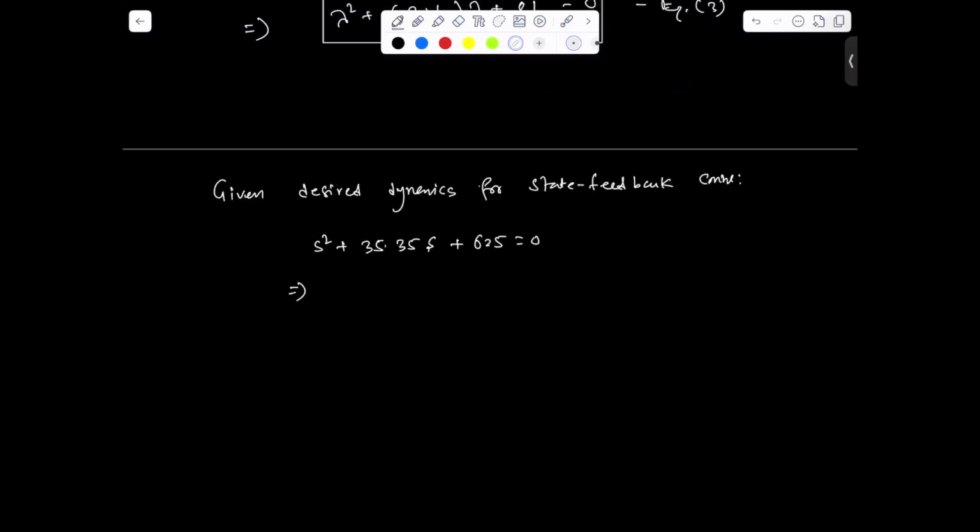And from this, we can find s1, s2, two poles, minus 17.68 plus minus 17.68i. From the poles location, it is quite clear that the system is stable, right? So there is oscillation initially, but over time it will decay to 0 since this is a stable system, all poles in the left half plane.